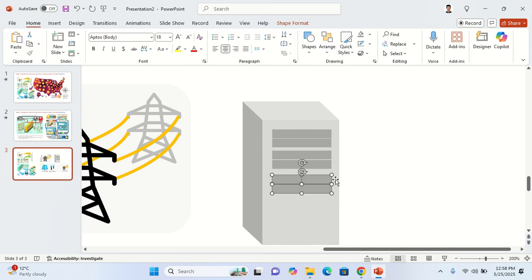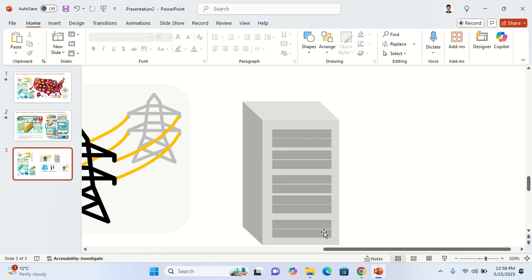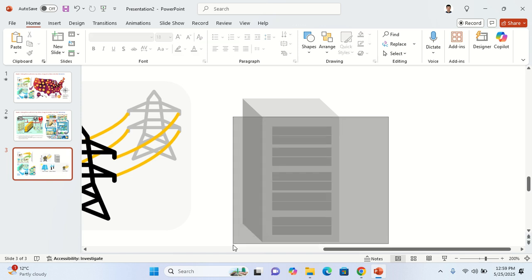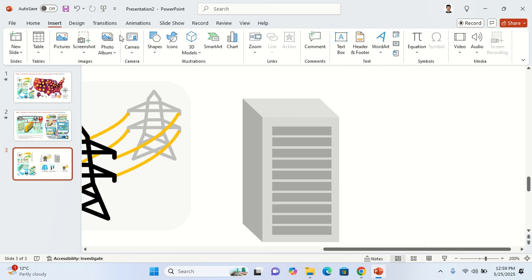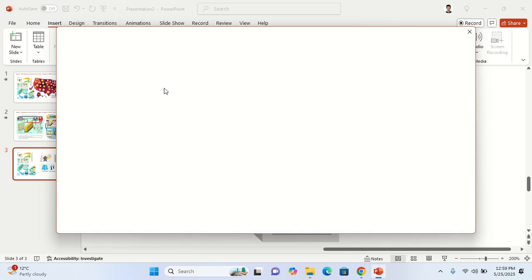What you can do is make two of those, copy, paste, copy, and then let's copy 4 of those and then paste it here. All you gotta do is ensure that the bottom one is where you want and the first one is where you want. Select all of that and then simply go to align, and then align, distribute vertically. That's done.